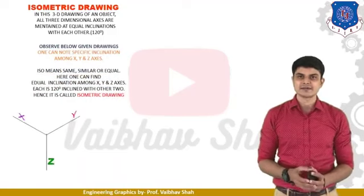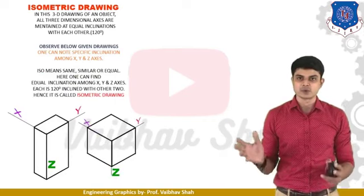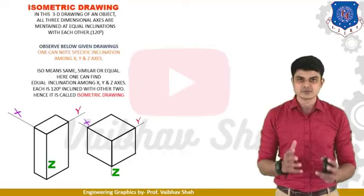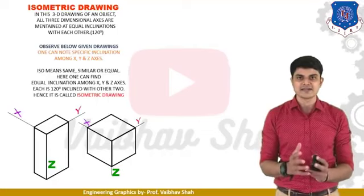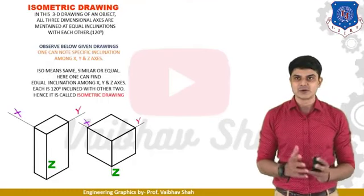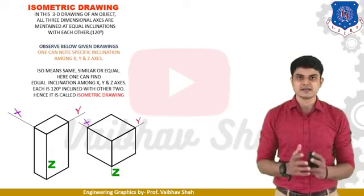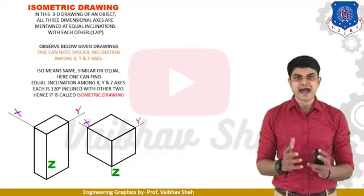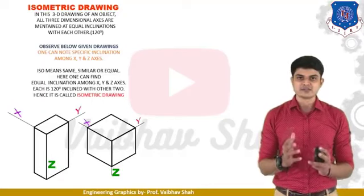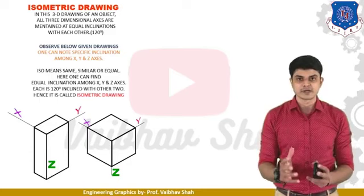So let us understand this isometric drawing. As you can see, I have two objects on my left, and these two objects have three axes x, y and z. When I draw these two objects by keeping the three axes at 120 degrees apart, it is known as your isometric drawing. Iso means equal or similar. As you can see, the three axes have a similar angle between them. So that's why it is known as isometric drawing. Isometric drawings are actually drawn to understand the shape, size and the overview of an object before its production.